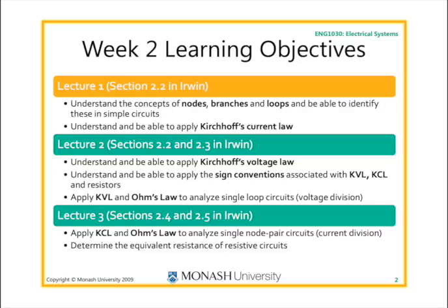What I say is you shouldn't have two nodes separated only by wire, only by interconnect, because the interconnect isn't anything of significance. So I can see you might have said 8 because you called this a node and this a node and this a node and maybe even that and that and that. But the reality is this whole thing up the top there is all just connected to each other by wire. It would all be at exactly the same voltage, and therefore that whole thing is just one node, and this whole thing down here is just another node, node 2. So really there are only 2 nodes in that circuit.